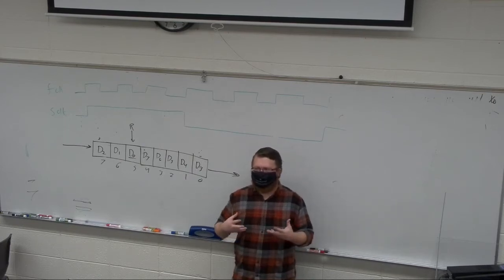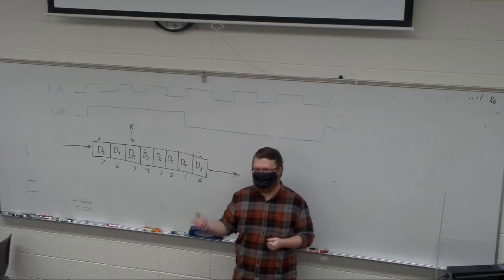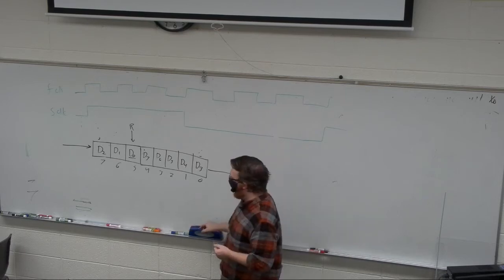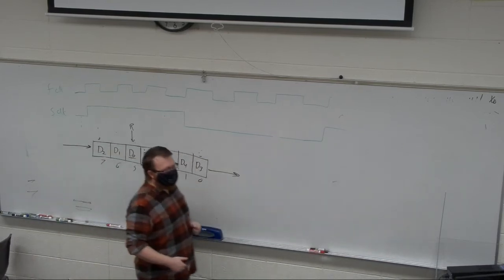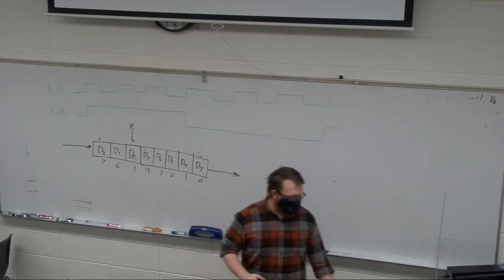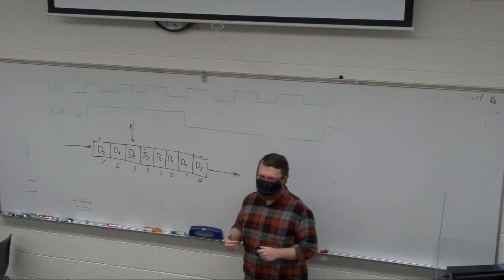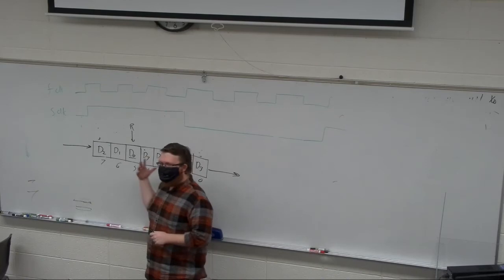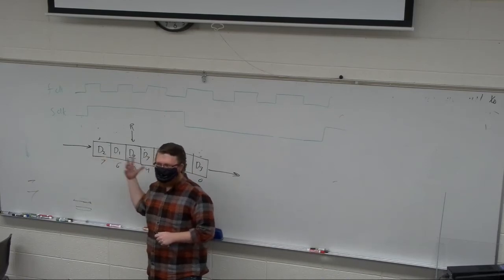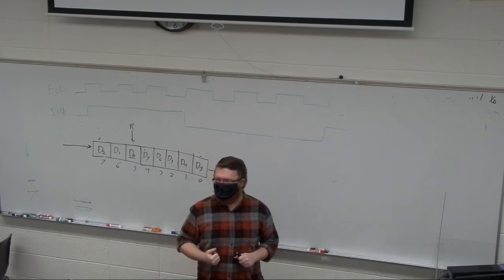So I'll start off by pointing out some of the things that you want to be concerned of, and then I may actually assign you to write an asynchronous FIFO. They're kind of fun, but they're also kind of annoying. So the first thing that we want to be aware of is that we do want to use something that we call almost full or almost empty flags. This lets whatever data stream know that it's maybe running out of time, right?